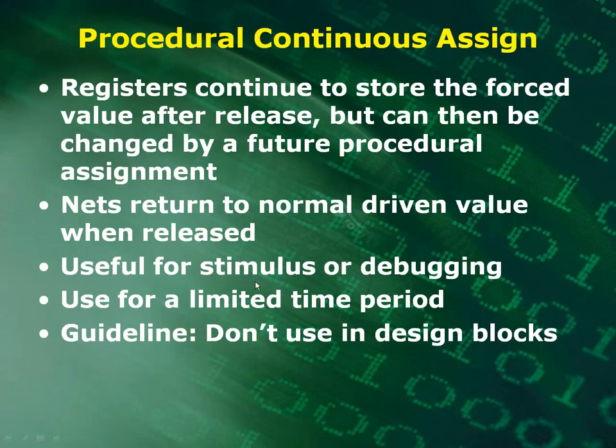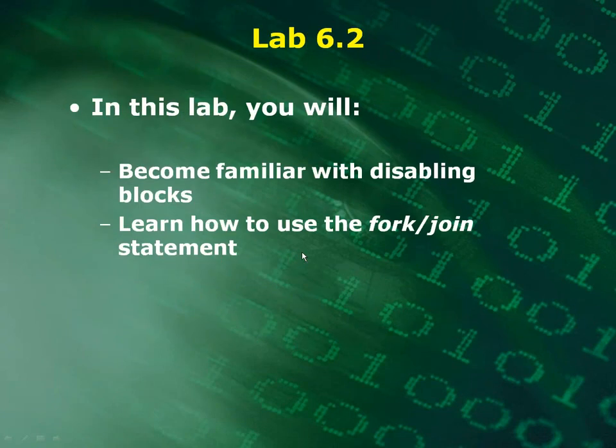These force and release statements are very useful in simulation or debugging, and you should only use them for a limited time period, and do not use them in your design blocks when you're going to write synthesizable code. You don't use them in that. Very useful though for simulation. One useful feature is making sure you're forcing certain registers in your design to a known value on reset for your simulation. So in Lab 6.2, I want you to become familiar with disabling blocks and to learn how to use the fork join statement.